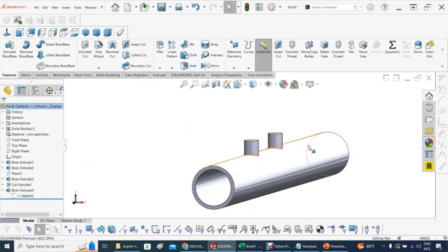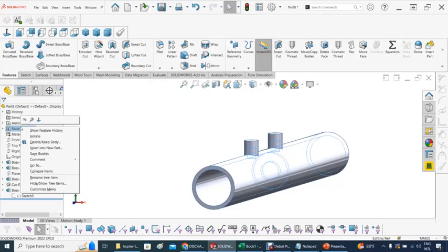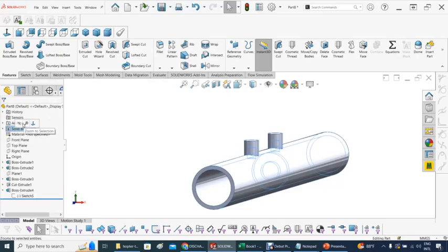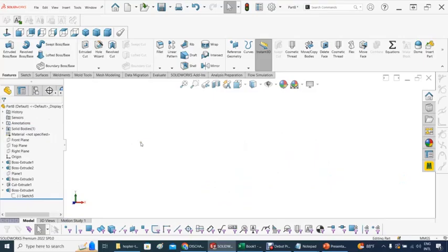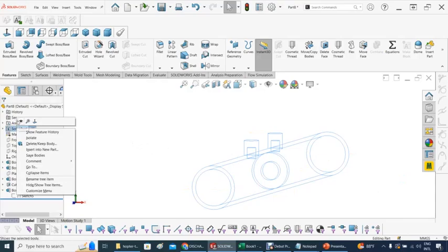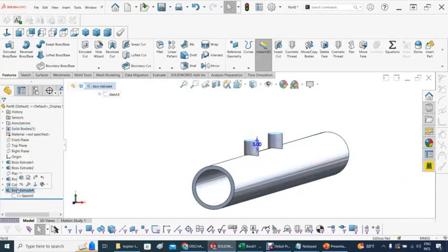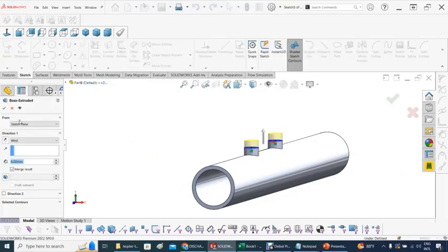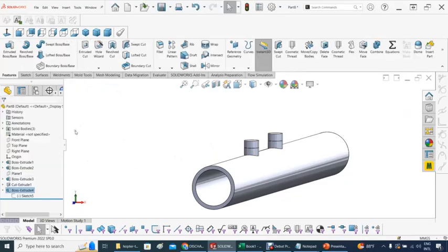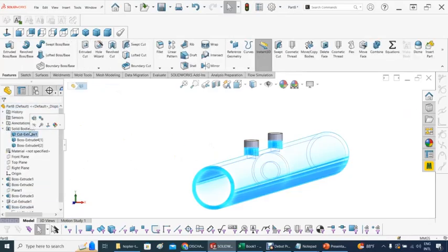And this is interesting. If you merge them, then, for example, it's one body. If I hide the body, let's say you hide everything, and that's not good because I want to see those seals at one point in time. So let's go back here to edit that. Let's show the whole thing, and instead of having that merge, we want them like another entity, like another body, and we're gonna accept that. So we got two bodies there. We're gonna accept them, and now all of a sudden we have three bodies, which is the pipe and the two seals, and that's kind of nice.